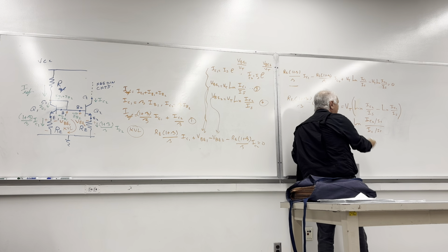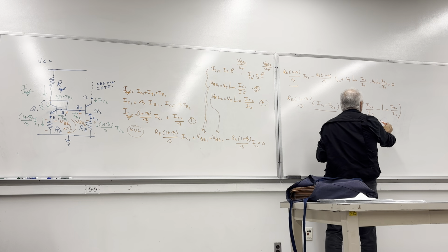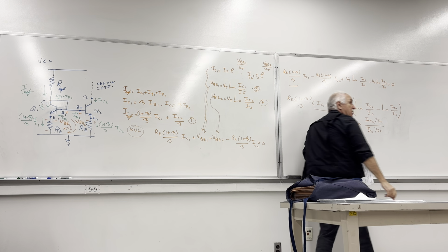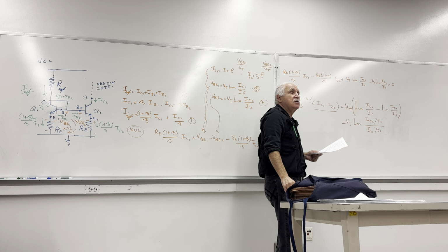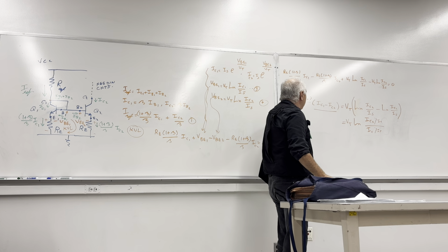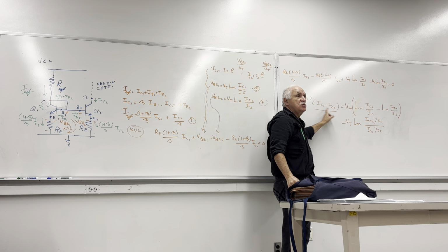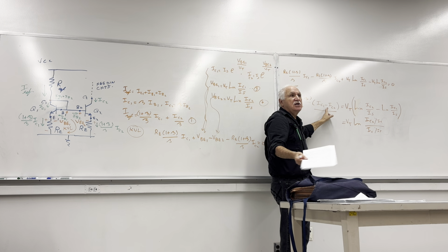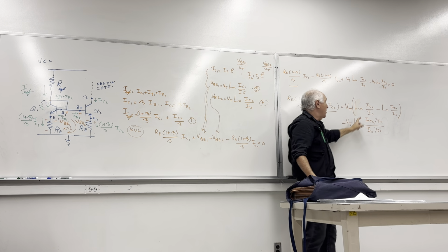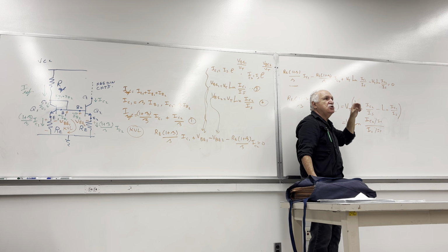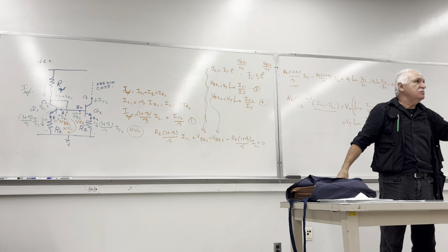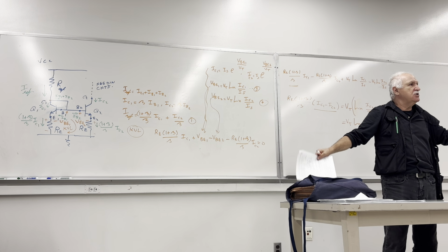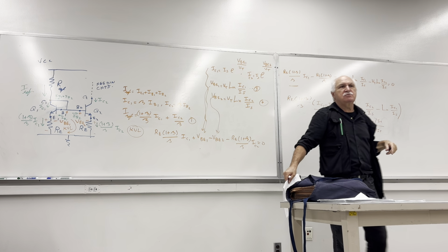Okay, from top and bottom in here, interesting, the IS will cancel out, which is a very significant thing. The reason is our collector currents will be practically independent of the reverse saturation current in each transistor. Even if they change with temperature, and they do, the ISs change with temperature, they cancel each other out.